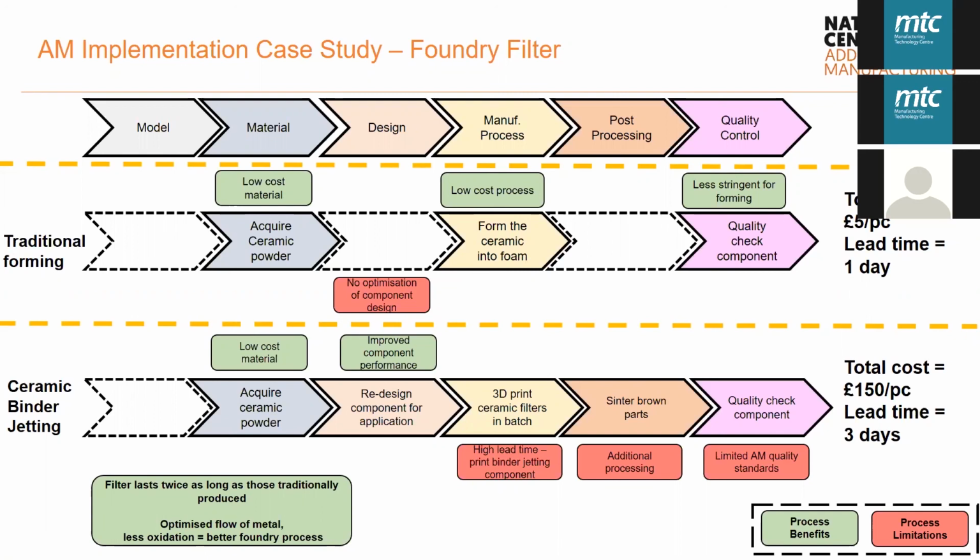That's true. There's also in situ process monitoring as well, which sometimes can pick up areas where there is high thermal activity or high temperature, and you can adapt melting strategies to try and reduce warpage downstream. Brilliant. All right, thanks for that, Dainis.